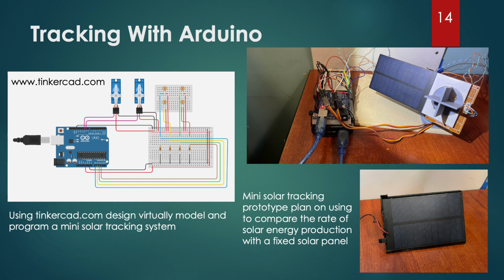Solar tracking uses complex instruments such as computers, sensors, and motors to determine the location of the sun and to align with it. The use of sensors can provide feedback information about the sun to the computer, so that the computer can process complicated algorithms that enable the model to follow and track the sunlight.